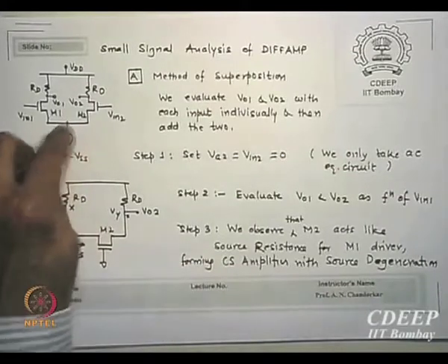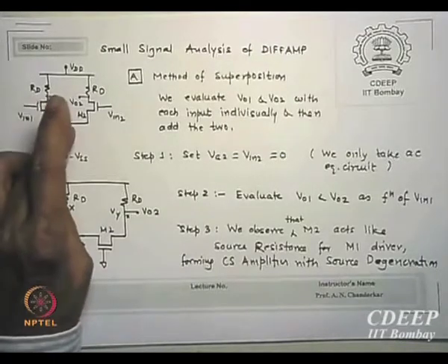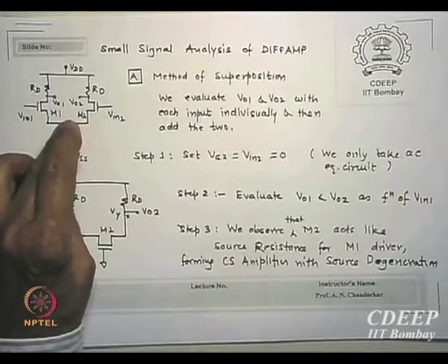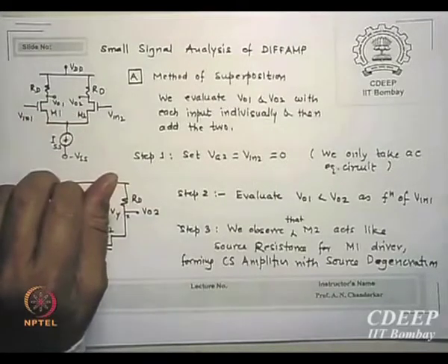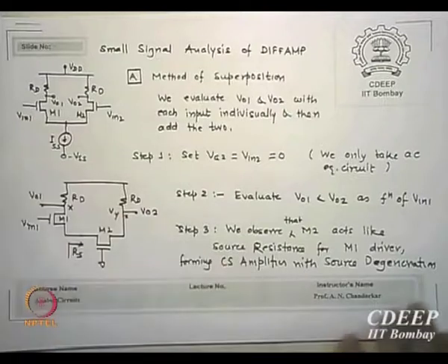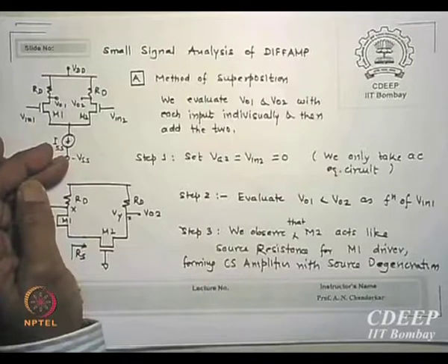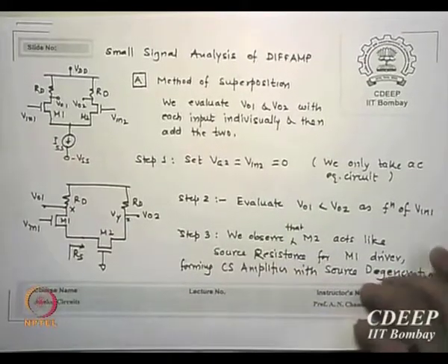I am not saying it's an AC ground there. The reason why I am not calling it that is because there is a voltage here right now which I don't know how much it is. Because of the signal I am getting a signal voltage here. There is an AC signal going on there, that cannot be grounded. There is a current flow, there is a resistance drop, so I cannot call it ground there. But this is a DC current. So what path? Infinite resistance. Is that clear? Even if it is taken, it doesn't hurt me. No current in that arm.